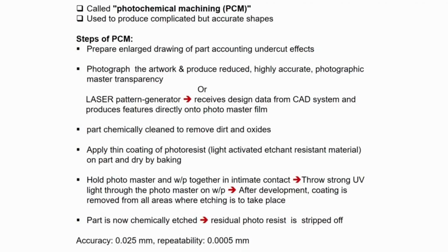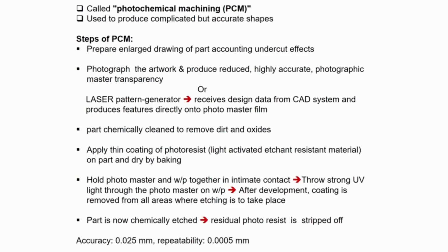After that, the photomaster film and workpiece are kept together in intimate contact, and very strong ultraviolet ray is thrown through the photomaster onto the workpiece.